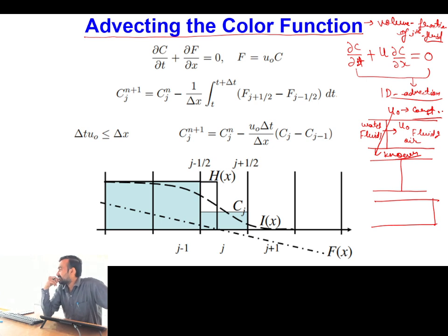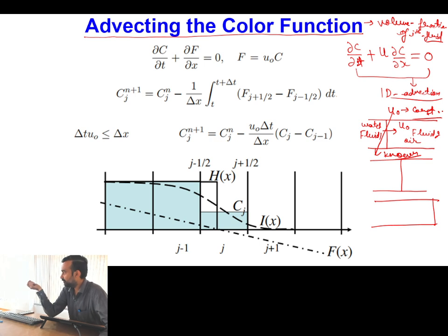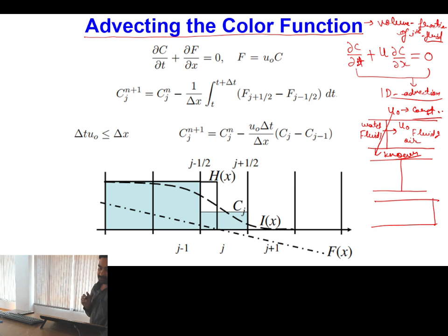And at the same time we know that if we have to determine the velocity field using numerical solvers, then we have to solve the continuity and momentum equations simultaneously. We are assuming for the time being that velocity is known, because here our major interest is to study the advection scheme for the interface, like we have done in the case of the scalar transport equation. However, in an actual scenario, whenever you solve this particular equation, along with it you have to simultaneously solve the continuity and momentum equations in order to determine the value of u. All are clear with this point?